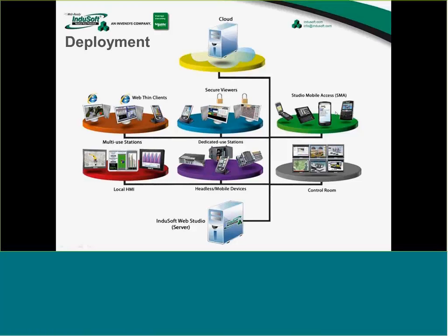What's really neat is that some of our competitors have given the capability to do tablets and whatnot, but they make you download an app. We don't make you download an app. We don't have to update the app, you don't have to update the app, and the customers don't have to update the app, because it's just a browser. You open up the browser and point it back at the runtime server, whether it's an HMI on a machine, a headless device in a control cabinet somewhere, or a server running. You would point that browser back at that running version of InduSoft Web Studio, and then see that on the browser. So it's real nice because you don't have to maintain that app or download that app. Just open up the browser.